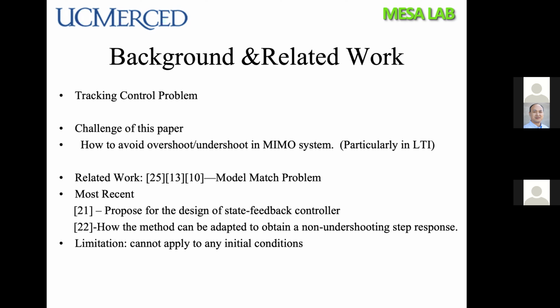The framework proposed here shows that for MIMO LTI systems, the objectives of achieving a short settling time while at the same time avoiding overshoot and undershoot can be met. The problem of improving the shape of the step response curve for LTI systems is as old as control theory. For example, heating or cooling systems, elevator or satellite positioning. The common element in these problems involves designing a control input for the system to make the output take a certain desired target value and keep it there.